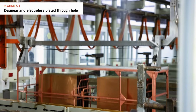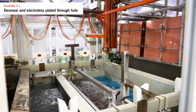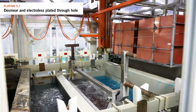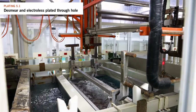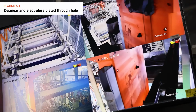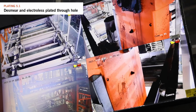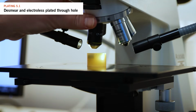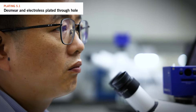This process can be done vertically for multilayer products or horizontally for HDI products. This process, like other chemical processes, depends on precise controls due to its speciality, plating metal on non-metallic and metallic surfaces. Having this step under control is crucial because without this thin deposit we won't have connections through the holes. We use the backlight test, which is a method to check the deposit. Relying only on microsections is challenging as the thin deposit is hard to measure, and using a probe to measure it risks damaging the deposit.